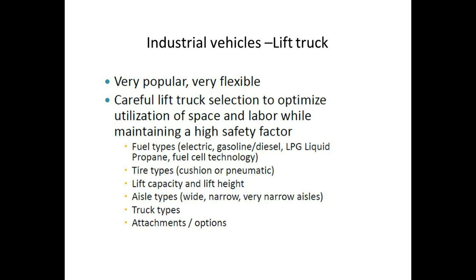Then you have to choose the tire type, whether cushioned or pneumatic, and the lift capacity. This is basically the design capacity, depending on the material type. For example, if you want to move a 1 ton unit load from one place to another, then you choose, with a factor of safety, let's say a 1.5 ton lifter.